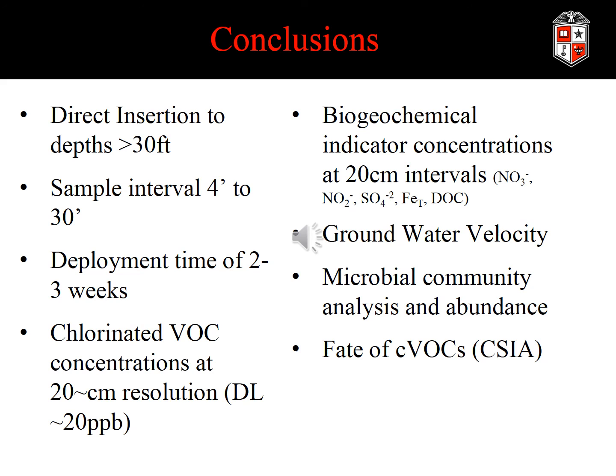These include things like nitrate, nitrite, sulfate, iron, DOC. But really there's no limit to what you can look for as long as you have adequate water to test. There is a finite amount of water returned from each depth, so there is some selection that has to go on. But most of these analyses only use a very small amount of water, which would allow you to look at a number of other species. There are also 2 cells per depth, so you get duplicate analysis for each of these.